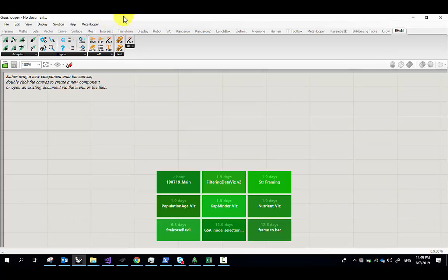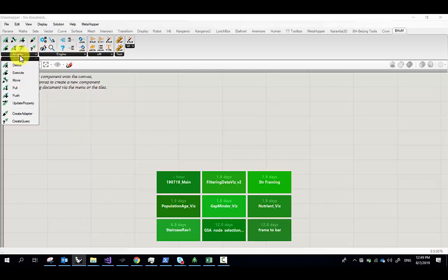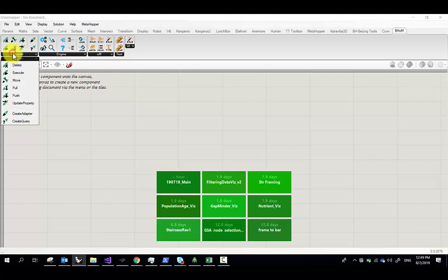So if I want to talk to another program, that's called an adapter. The BHoM has four main parts. There's objects, OM, engine, which is like algorithms that take in objects and they do work with them. And then there's adapters, which connect the objects to other parts, other software. So today we're going to want to create an adapter.